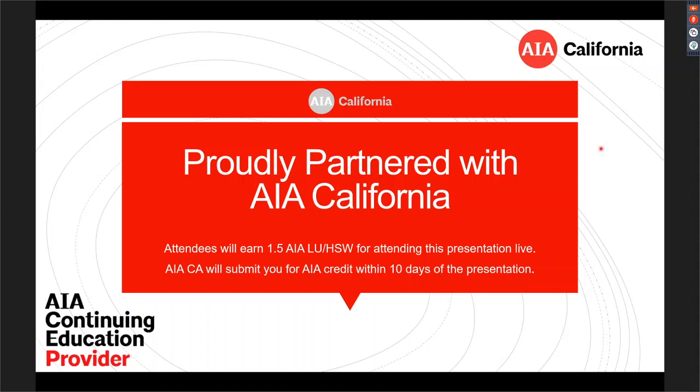Perfect. So, question going back to a UL listing. Does a change in UL fire stopping, is it an ACD or is it an NMA? For a fire stopping detail? The question reads, does the change in UL fire stopping, is that an ACD or an NMA? It depends if they're changing the detail, if they're changing the material. If you're going from a fire stopping change, just changing the fire stopping itself to a different product, if it meets the same requirements, it's just an NMA. It's just a substitution at that point.